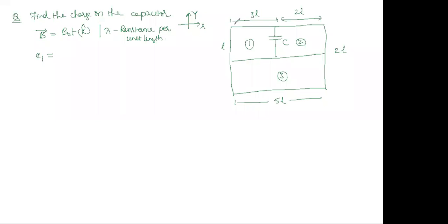All of you look into that, don't write anything. So what is the EMF in this first one here? A into dB by dt. What is the area? 3L square. What is dB by dt? B naught. If I assume that B naught L square is equal to small e, this is 3e. What about E2? 4e. This is L. This total is 2L. 2e.